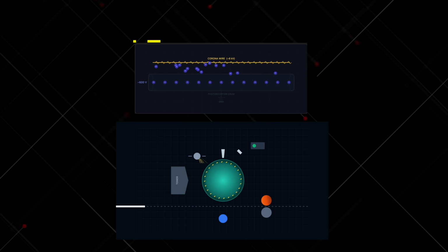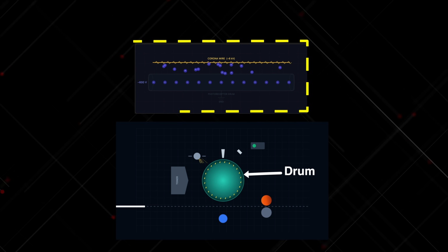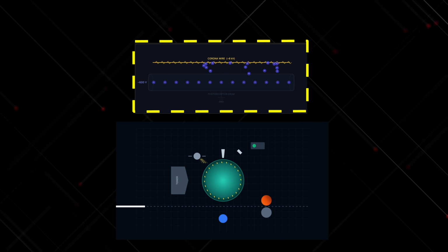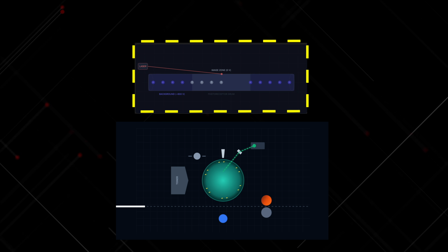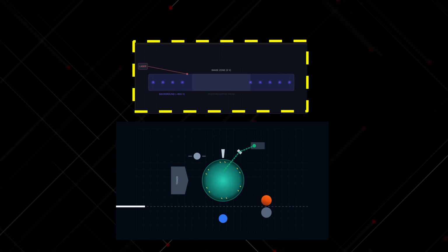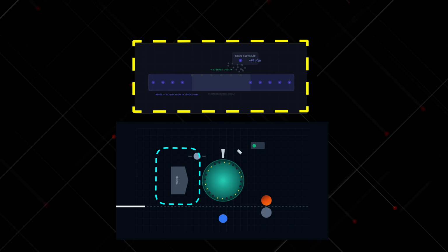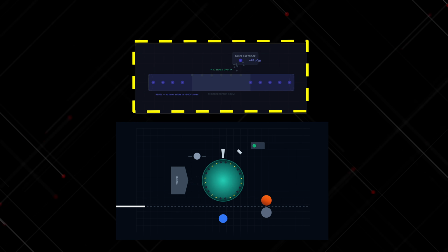So similarly, the same electrostatic force also works in the laser printer. So in the laser printers, if you see, then we have the drum. So initially before printing, by applying the high voltage, this drum is charged negatively. And now using the laser, the part where we want to form the image, from those part, these negatively charged particles are removed. So in these printers, as you know, the toner is used for the printing. So this toner is also negatively charged.